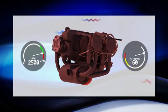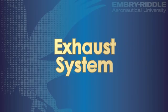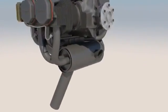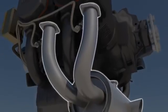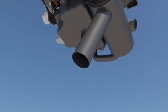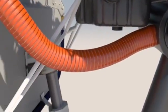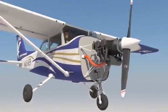causing higher temperatures. The last step in the four-stroke cycle is the exhaust. The exhaust system has a dual purpose in most general aviation airplanes. As expected, the exhaust system does allow the hot exhaust gases in the cylinder to escape the engine in a quiet manner. Additionally, as we'll talk about later, the exhaust system also provides heat to the cabin.